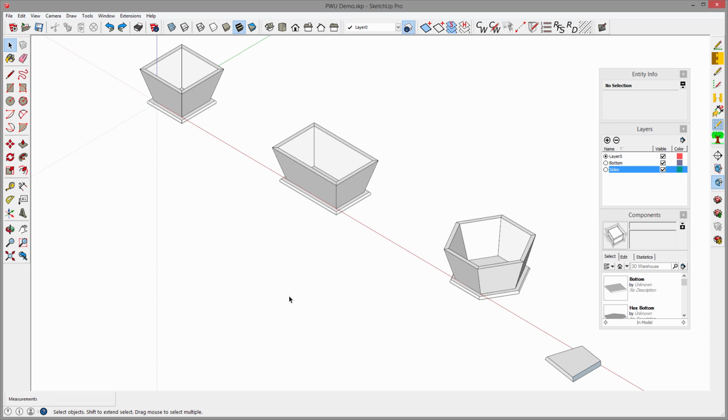Morning. This morning I'm going to show you how to create some shapes that have compound miters, and also how to figure out what those compound miter angles are and how to set up your table saw to cut those angles. We're going to start by creating this four-sided box. The inside lower edge of this box is 4 inches on each side.